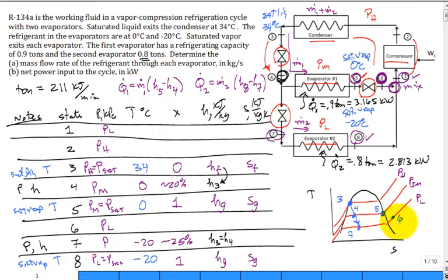All right. Now, the 8. For sure that it's superheated. The entropy has to increase. How do you know it's that much though? You would have to run the calculation and find out. You would have to compare the actual entropy. The other is you would look at the entropy at state 8, which is right here. And basically, actually the enthalpy will do it, not the entropy. Entropy is definitely going up, but the enthalpy, you can see that it's higher because it's isenthalpic. So enthalpy at 5 is higher, and that's equal to enthalpy at 6, and it's higher than at 8.